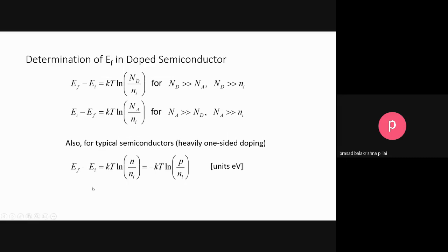So this kind of thing, we will see that later on. We will be using this when we discuss the PN junction, etc. One interesting thing, because I'll try to give you some numericals on this: you can see that when you increase the donor density, the gap will be increasing, and the Fermi level will approach towards the conduction band for the n-type material. And similarly, for p-type, the Fermi level will be going towards the valence band.